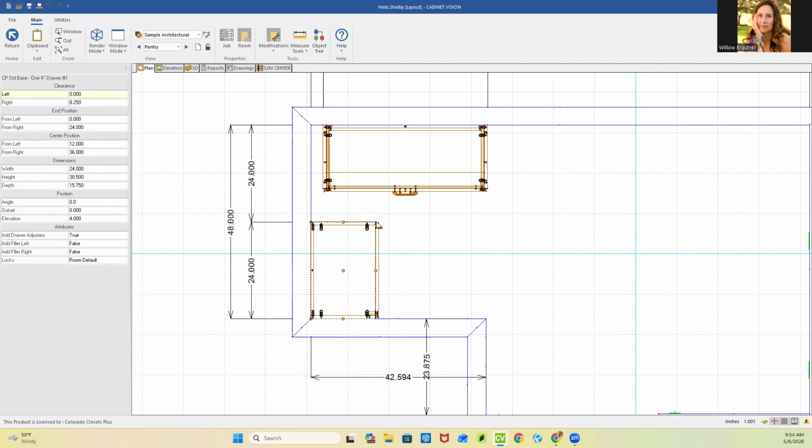All right, so then the question is, when this cabinet meets this one and forms a corner, how much of a gap do we want between the actual corner and the slab? I was told 3 inches. I've done three in the past. Sometimes I do two. Let's just do three today. It doesn't really matter.